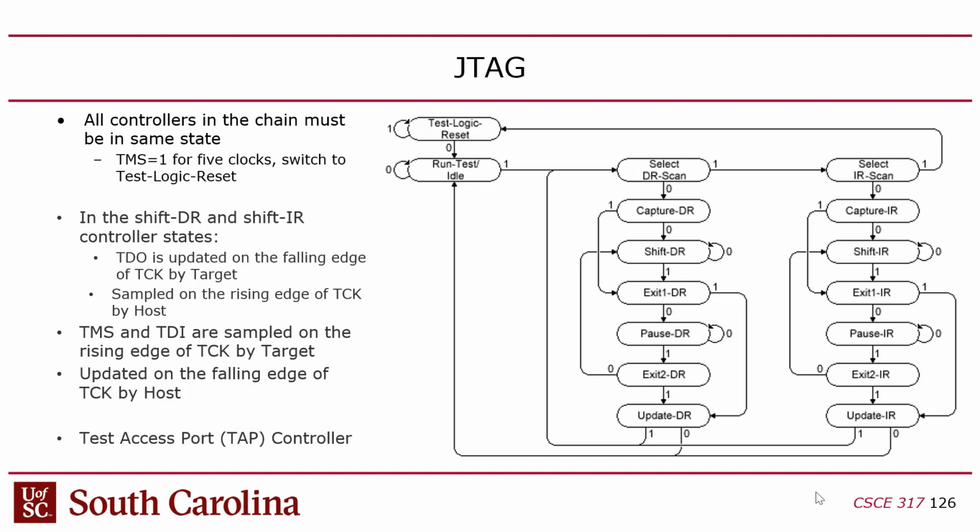Does that make sense? No matter what state I'm in, if I set the TMS to 1 for at least 5 cycles, I will get back to this start state no matter what state I happen to start in. So it doesn't matter where I'm at.